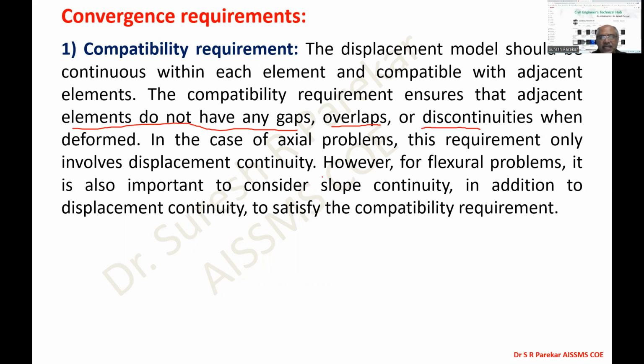Now you can see what is written here. If we go for axial members, we have only axial displacement, so we have to check the compatibility requirement only for axial displacement. But when we go for flexural members, we have to consider both displacement as well as slope continuity, and that is my compatibility requirement.